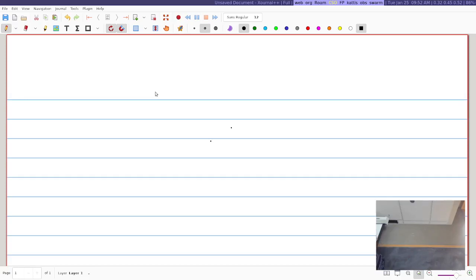If you want to put a constant value on some wire, instead of having it come from an input, you can say equals true or equals false. And you can do that even if you have a 16-bit bus, you can just say true, and it's just like all ones. So that can be useful.